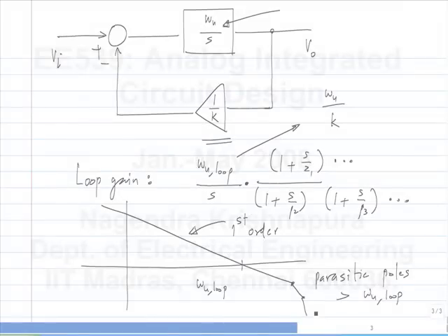So whenever you design a feedback system, this is a criterion that you have to follow. And also, on the DC side, the loop gain has to be large enough. So in reality, you will not get this. It will flatten out somewhere. Now it can flatten out at a lower or a higher value. That gives you lower or higher accuracy.